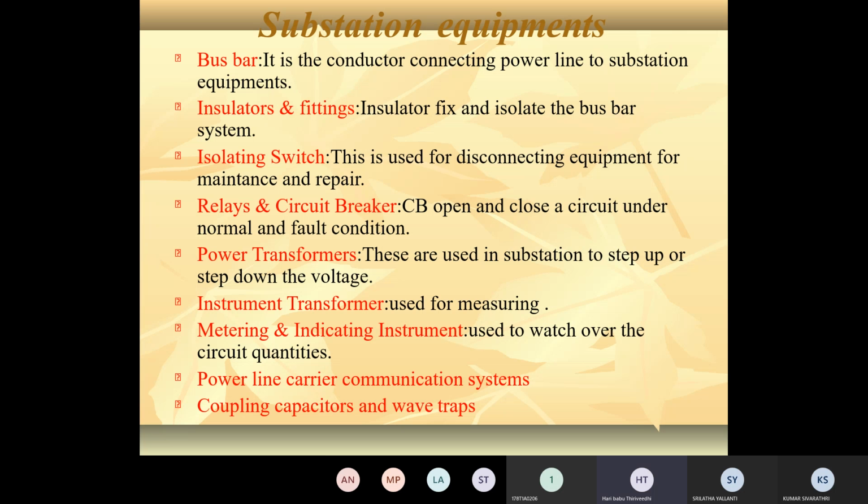At the generating station it is only to step up the voltage; everywhere else, it is to step down the voltage. Usually for power transformers we use natural cooling or oil cooling, right? The transformer's rating is always greater than 10 MVA. So that may be utilized in the power transformer.